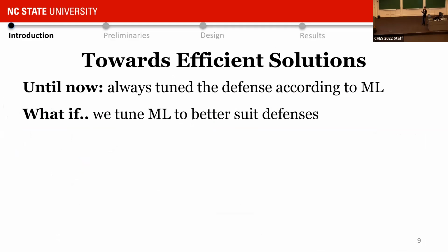And that has been a big problem. For example, in one of the research works, because of the absence of modular arithmetic, they had to specifically implement a hiding countermeasure to prevent the sign bit leakage. Well, the solution is you can always do a Boolean masking for the entire neural network, but that is going to be extremely expensive because you are trying to perform Boolean masking on arithmetic operations.